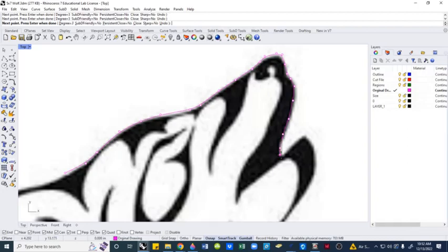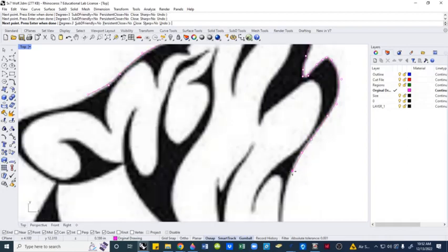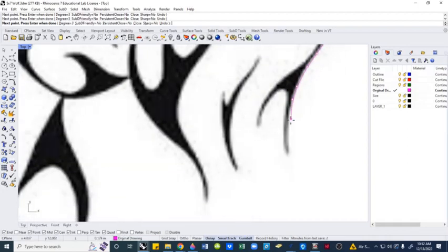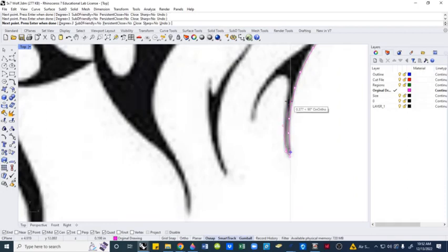If you do have a sharp corner, I try to use a 3-point click, and we're going to be coming to one down here. So as I get to it, I'm going to click, click, and back. That's going to give me a sharp corner to reference off. Same thing, 1, 2, 3. Let's say I mess up and put one over here. I can just go U space for undo. If you have more than one that you need to undo, you can do that as well.